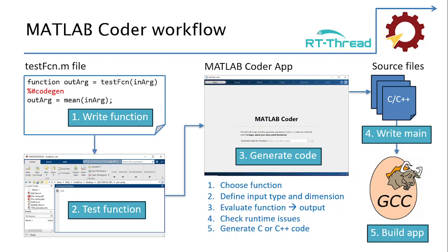Then we let the MATLAB Coder application inside MATLAB do the remaining job of code generation. The output will be C or C++ code, which is quite portable, so that we can integrate it into our base code, then build it into an executable image and run it on our hardware. Okay, so today we will show this.